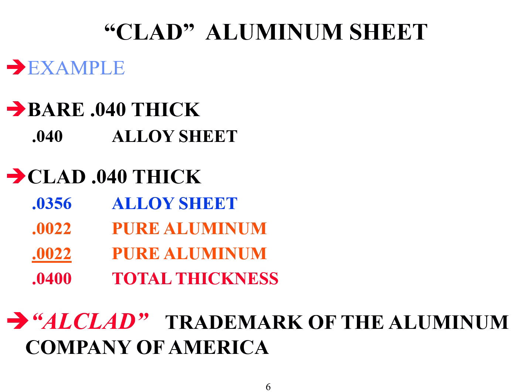That's just simply the trademark of the Aluminum Company of America. Each company that produces may change the name a little bit, but the term clad means that there's pure aluminum pressed under tremendous heat and pressure on each side of that alloy to make it more corrosion resistant. We must be careful not to scratch it.